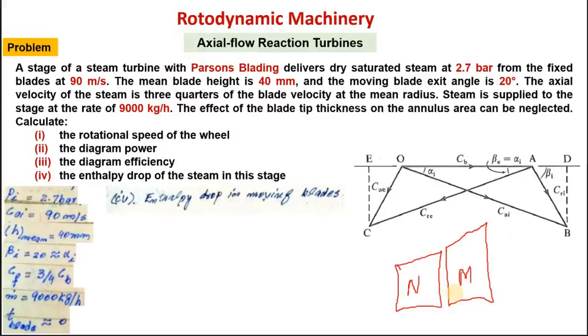When pressure is dropping, volume is increasing. So in the volume flow rate, you have to increase the height, because volume is increasing, so you have to increase the area so that steam can occupy more volume. More volume of the steam can be occupied in larger space.